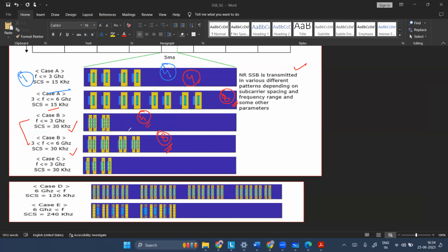This also relates to how, if we increase the subcarrier spacing, the frame stays fixed, but the slot count varies, and the slot duration in time is reduced every time you increase the subcarrier spacing.